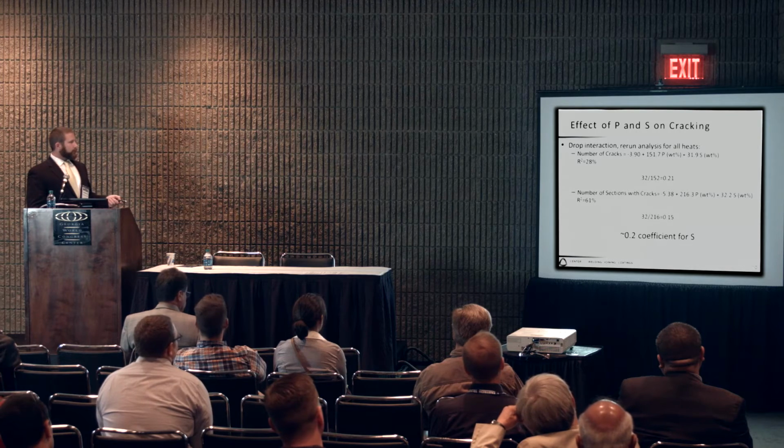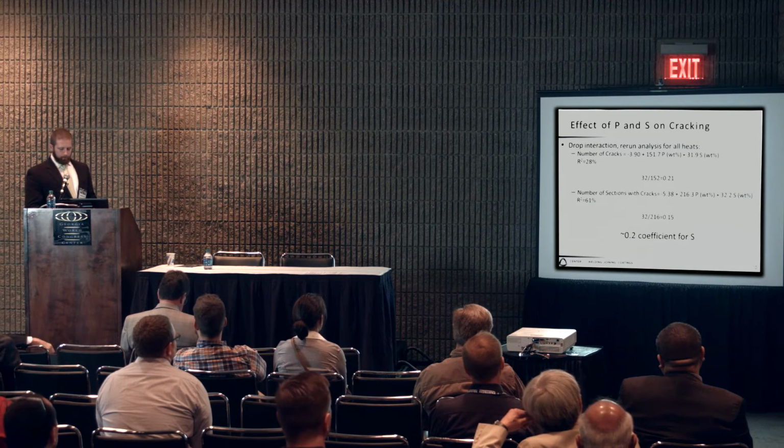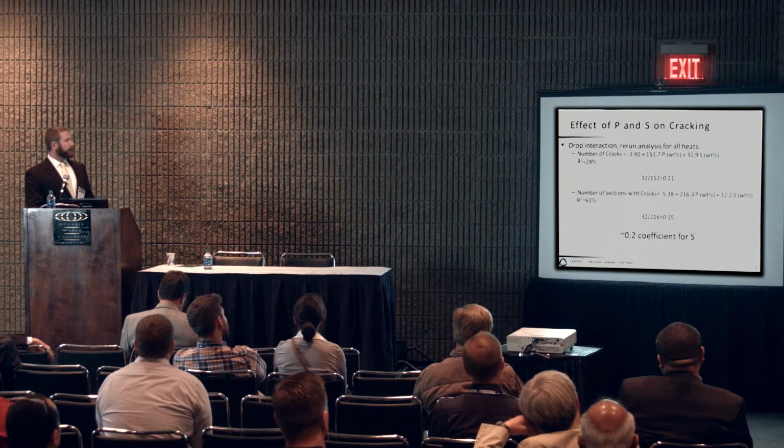So, generalizing these and not getting too specific, we chose a coefficient of 0.2 for sulfur to include on the weldability diagram.